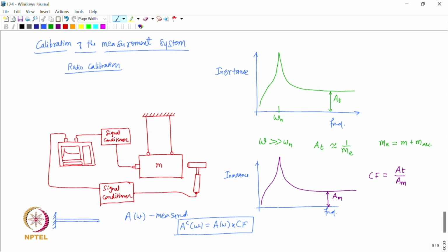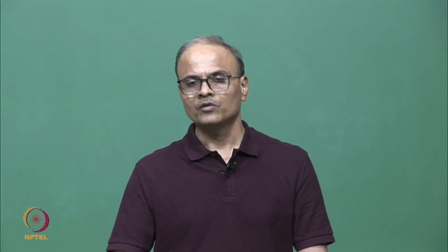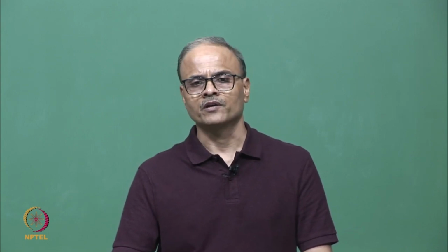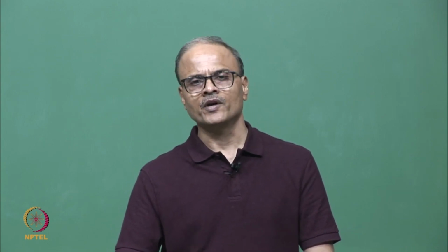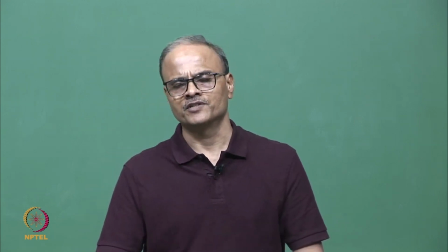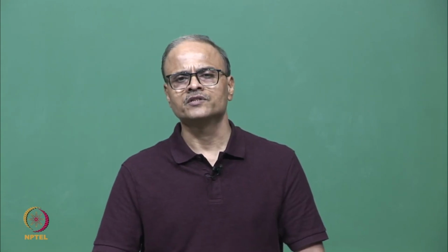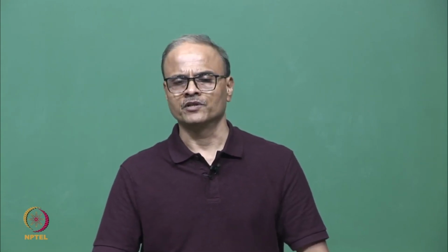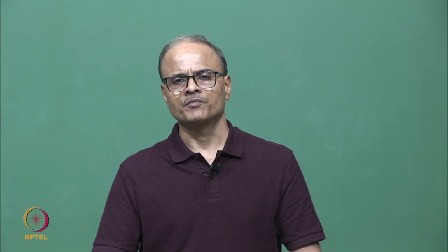This calibration factor takes into account any changes in the sensitivity associated with the force transducer of the hammer, the response transducer, right, and any other scaling factors which might be there in the measurement system. So all those factors are combined into a single calibration factor. Therefore, this method is quite effective in obtaining correct estimates of the measured FRF. So in this way today we looked at test planning for FRF measurement, and we discussed the several decisions that need to be made related to the measurement, right. Now we can stop here. Thank you.